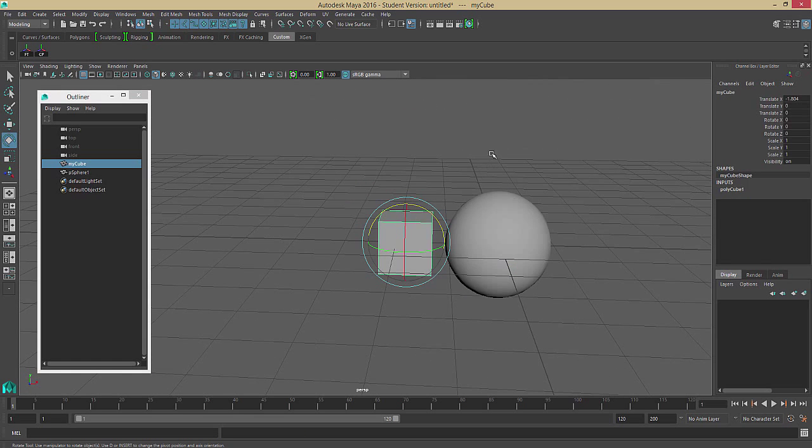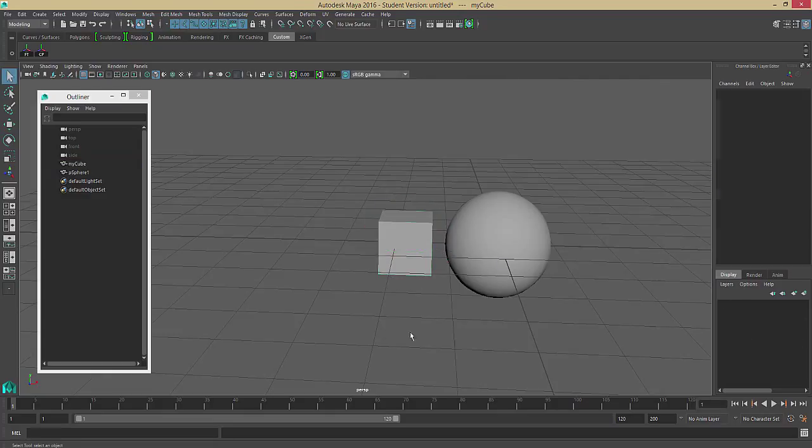The other thing we want to look at is our layers. Over here we have display layers. All you have to do to make a layer is select an object, and then over at these little icons, you have create a new layer and assign the selected object to that layer. You can also create a new layer that would just be an empty layer, and then you can move the selection down in a list, so you can move that particular object down into a different layer or down within the layer list.